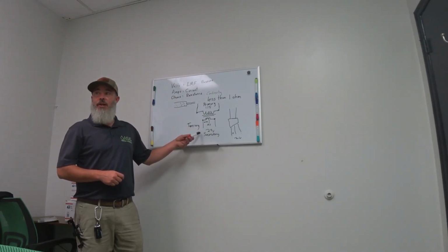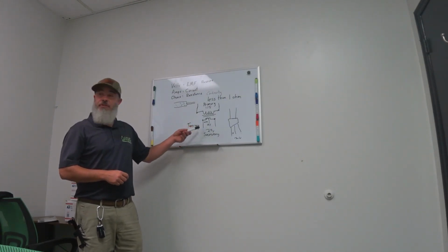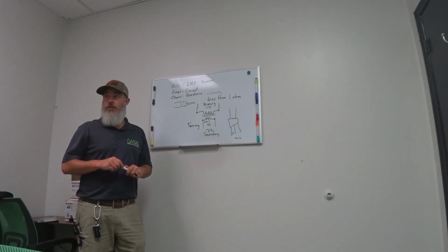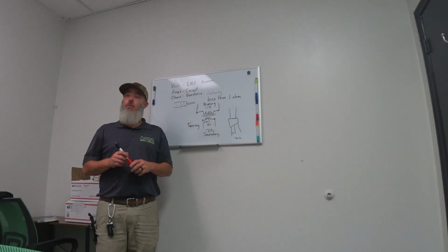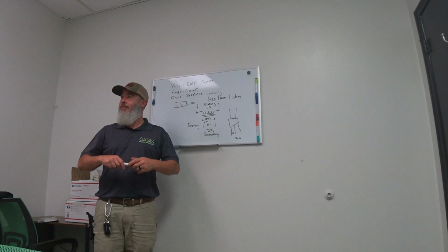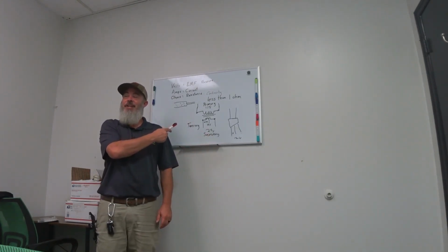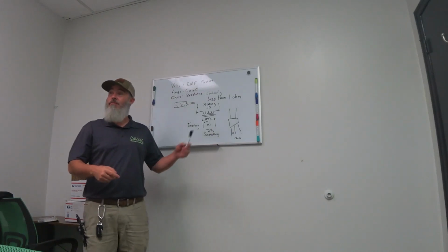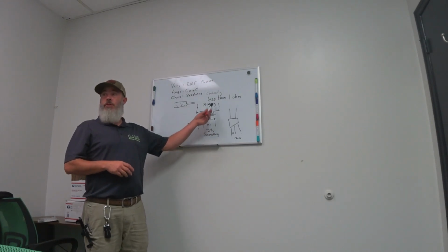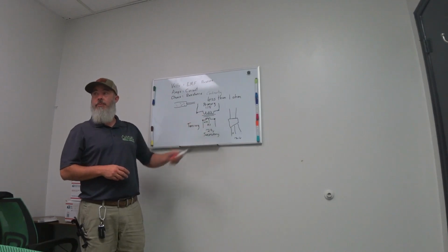When you're looking at a wiring diagram, you're going to see that coming from that transformer is going to be leading directly into the circuit board somewhere, and you're going to want to check voltage there. Is that board getting power? There's no lights on it. Why is it not getting power? Is a fuse blown, or is the transformer blown? Hey, we're getting power coming into the transformer, but nothing coming out. We've got a bad transformer.